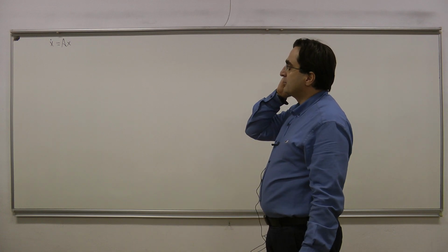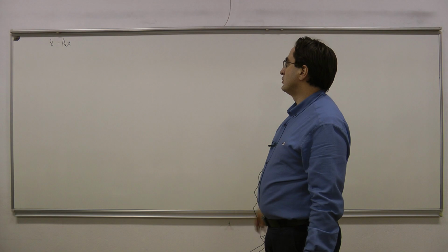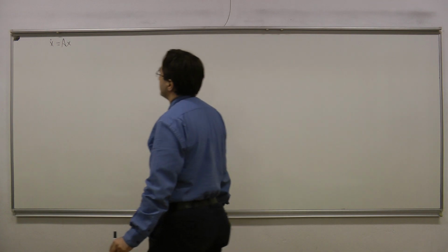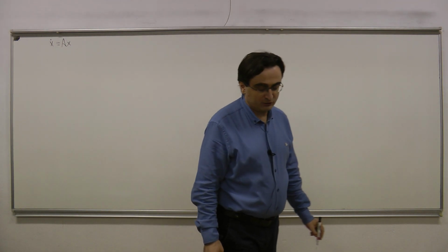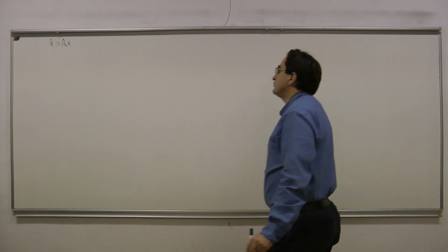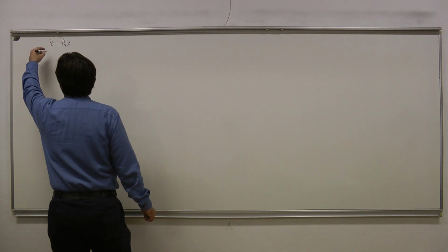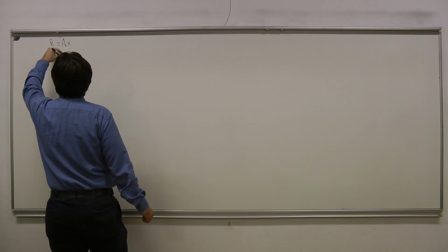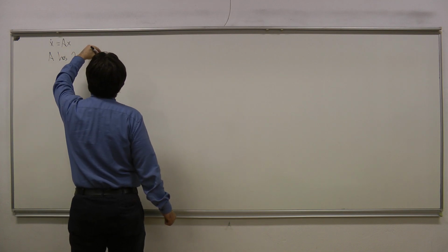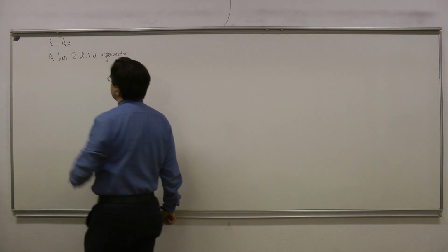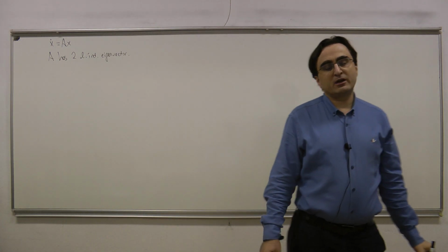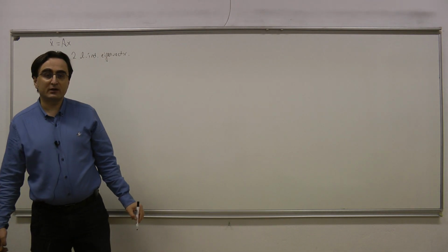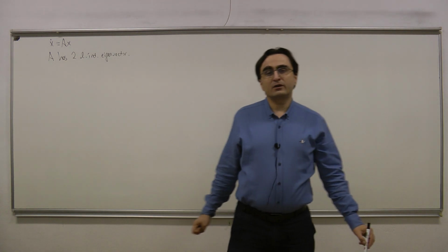And of course, we might have some initial conditions here. We would like to draw the phase-plane trajectories for different initial conditions, which means we would like to obtain the phase portrait of the system. We assume that this A matrix has two linearly independent eigenvectors. That is an assumption. In general, we might have the case when A has only a single linearly independent eigenvector, and we are not going to consider that in this course.